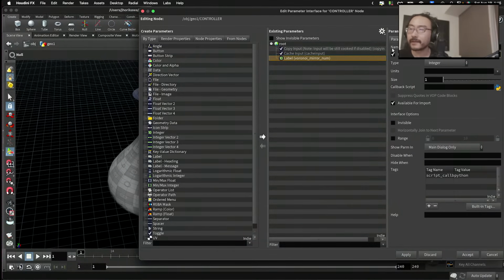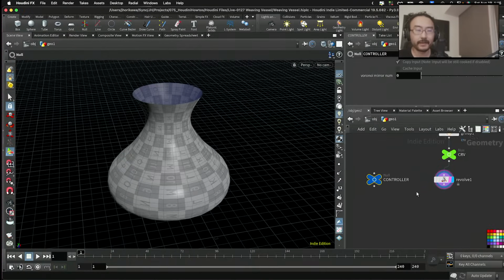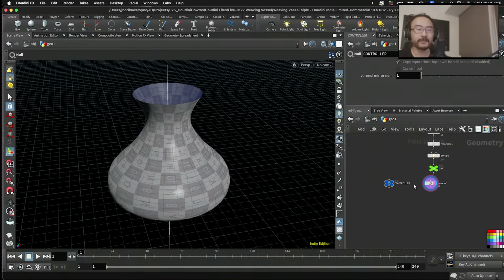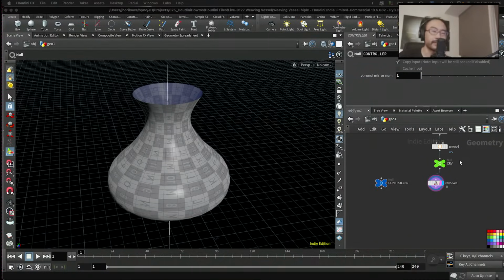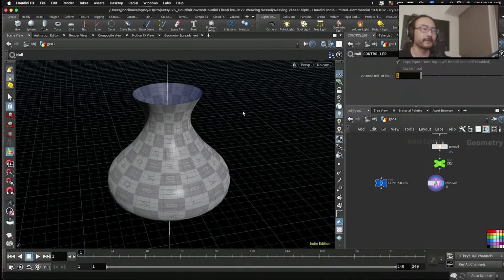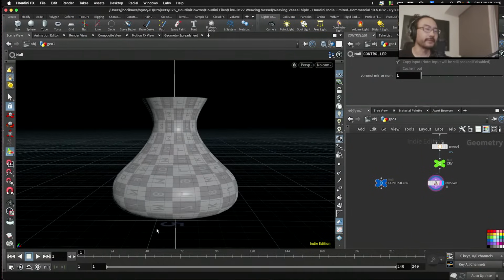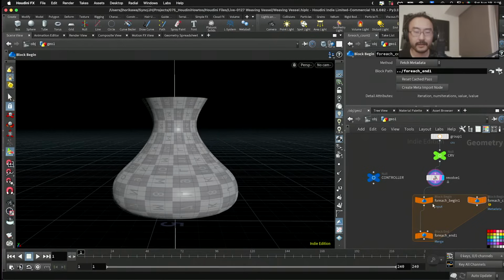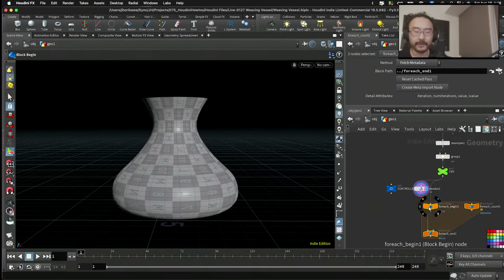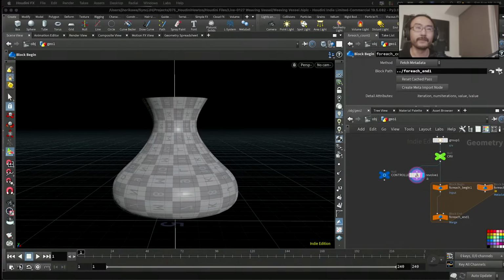Okay, so let's say 1 is the minimum, 10 is the maximum. Okay, then copy this value to create a mirrored shape. So if it's 1, I'm going to multiply by 2, meaning as an output you're going to split the surface into two. So let's create a for loop to create a looped mirrored shape. I'm going to use a for each number here. Probably I'm going to do the loop for the curve and do the revolve inside maybe.